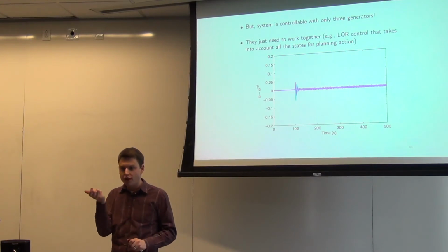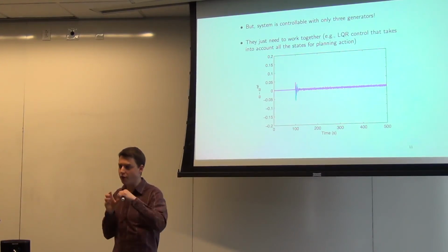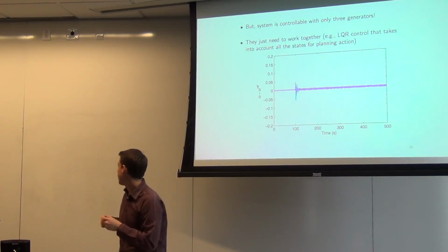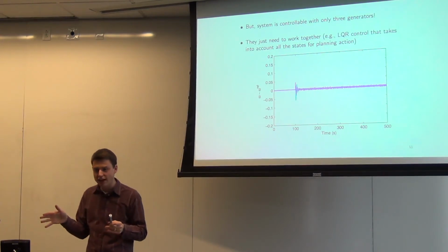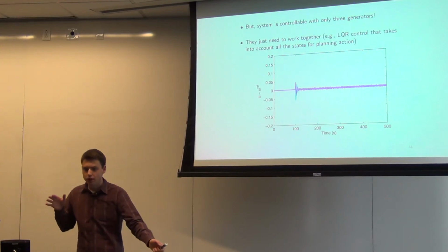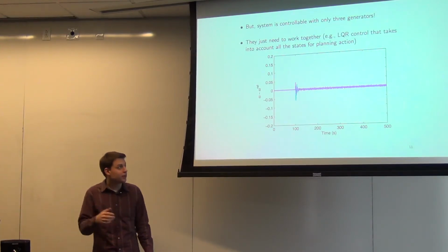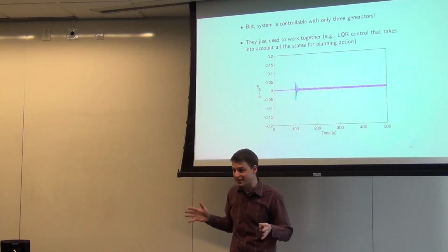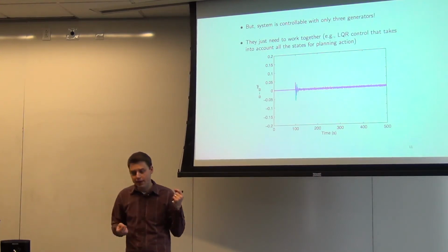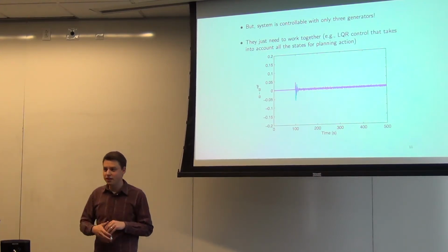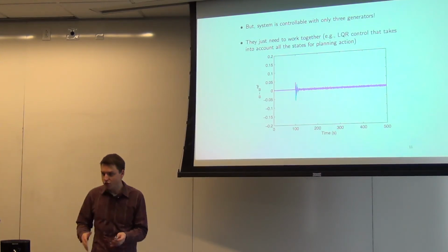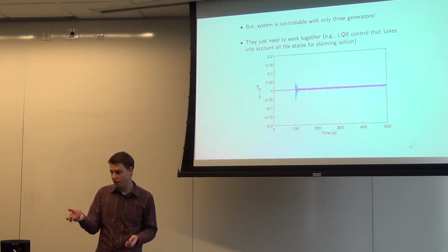It requires that the controllers at every generator know what's happening to all the others. Remember, the K matrix is a dense matrix, and so you actually need the state information not only at your own node, but everywhere else too. So what that implies is that if everyone would just communicate a little bit and say what's happening to me or to others, you could avert the situation. And I've heard folklore say that every outage that's happened in the last 20 years was perfectly preventable if all generators simultaneously knew what to do at the same time.